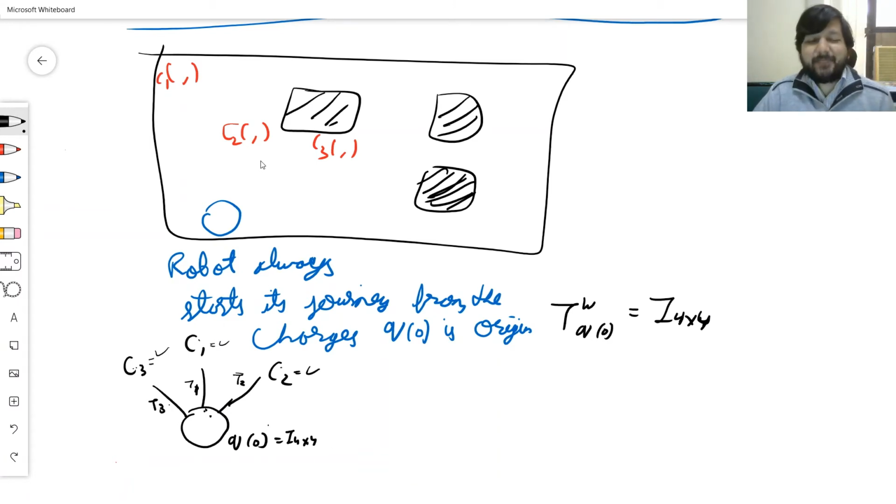So that's a cartoon representation of exactly what I said. And exactly the same thing could be done by stereo as well. So you take an image, you note down all the image corners, and because these are the image corners, I, using a stereo camera, calculate what the XYZ are in the camera frame of reference, and then you say that my position is identity, so I know these things.